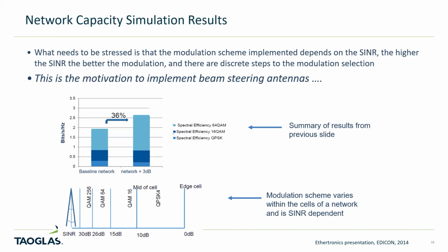The industry has already been doing beam steering and arrays on the base station and nodes for many years, but the client devices are typically that near omnidirectional, broad beamwidth antenna that's just blasting power in all directions. An interesting point to make is that within the dense nodes we find in a lot of urban areas nowadays, it is not weak signals that are the problem, it's interference.